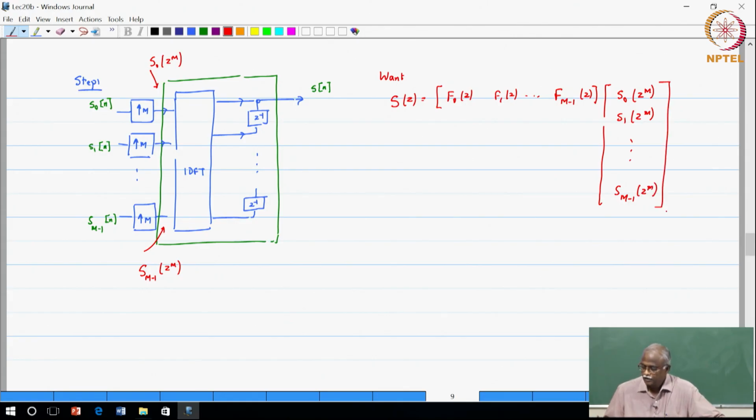This is the transmultiplexing operation. Whatever signal comes in, you upsample it, that gives you the column vector, and then you combine it using appropriate filters. Everyone's comfortable with this? Basically what you will get is a scalar after this operation, and that is what is represented as the frequency division multiplexed signal. So, now we have S naught, S1, Sm minus 1.